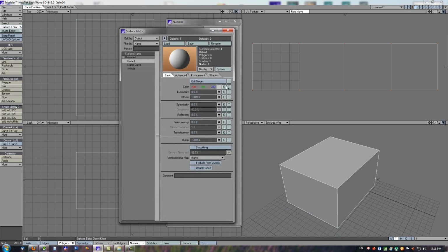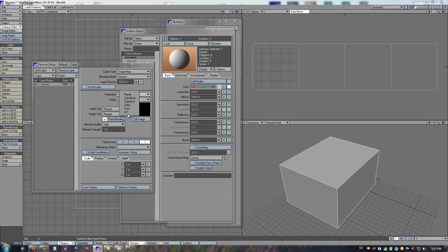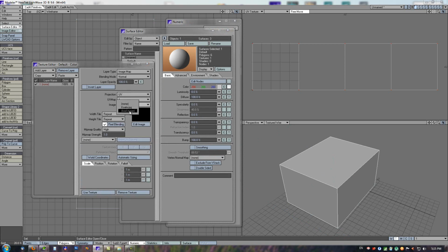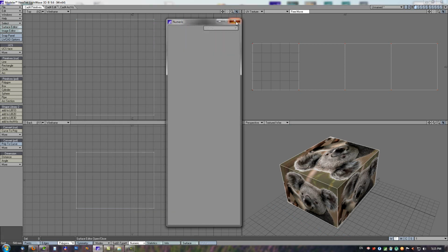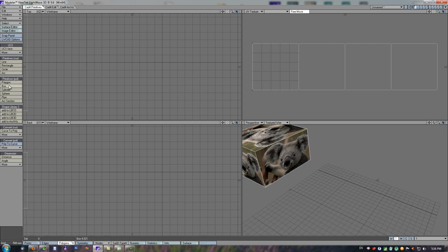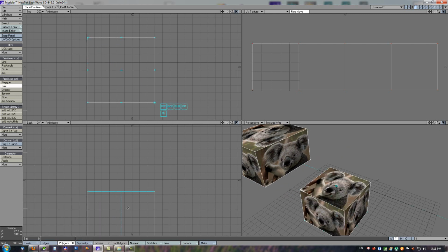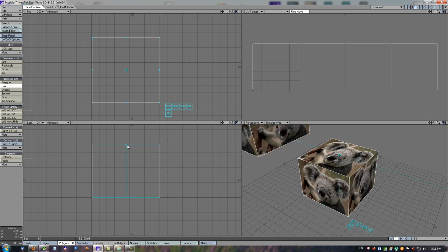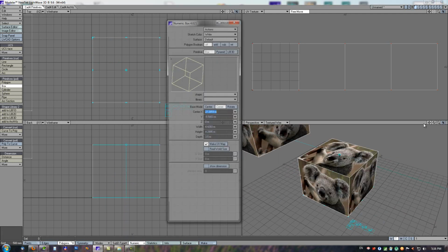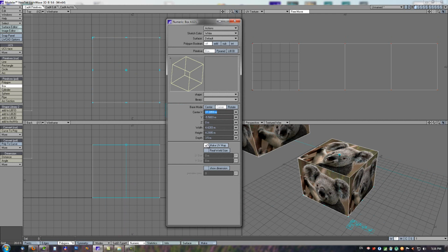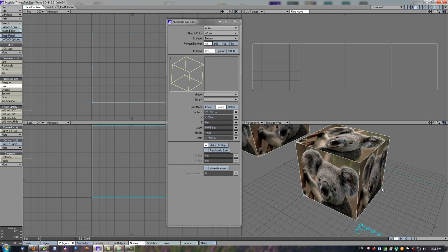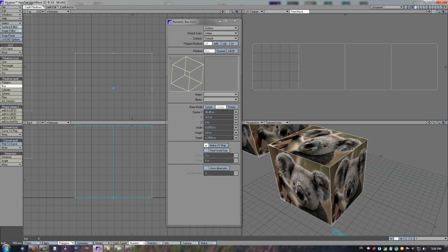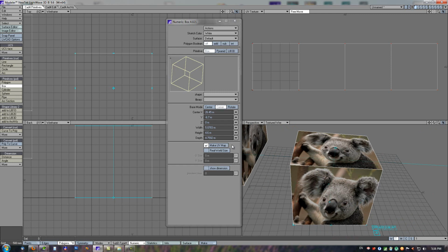I will apply some texture on this UV map so we can see this color picture. So when using any primitive tool now with the UV map real-time option, the object is automatically mapped, and we can enable real world size UV mapping.